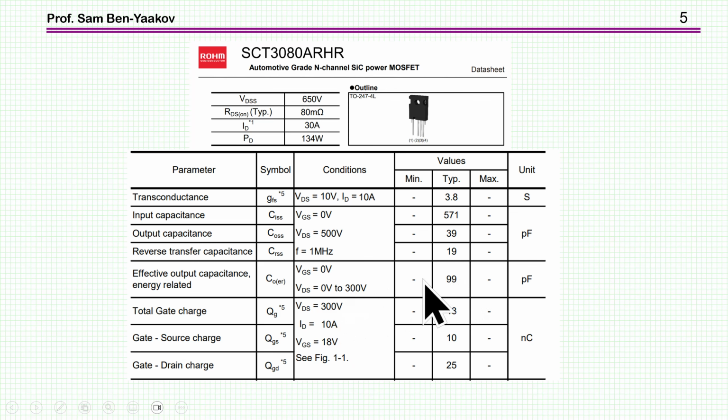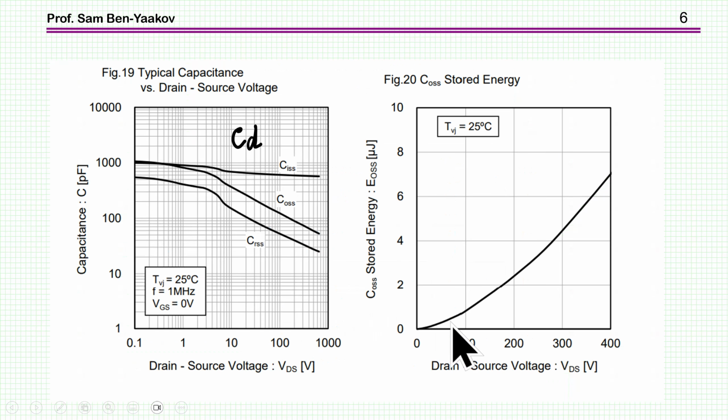This capacitance is going down with voltage. So the difference is not that large between the silicon carbide and the superjunction transistor, which is kind of surprising as a matter of fact. Also, this vendor is giving this classical differential or small signal capacitance, and also now this plot of energy stored as a function of the voltage across the output or across the capacitor.